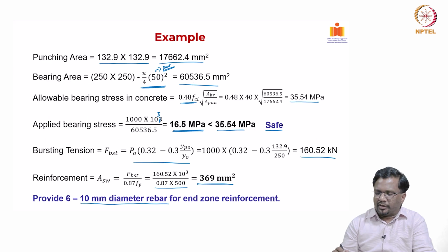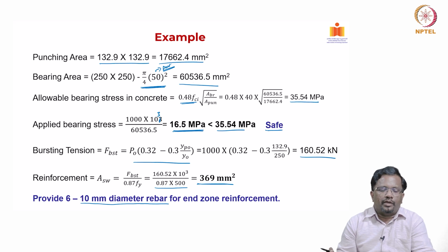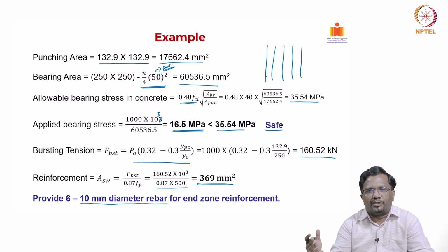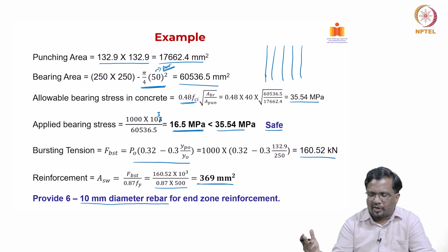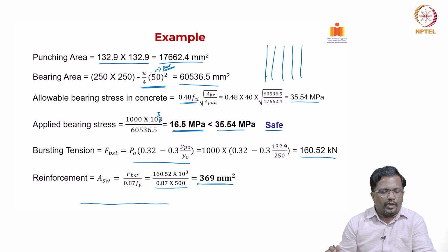Okay. So, basically we go ahead and put in the transverse direction, the same can be provided in the horizontal direction to actually confine the area. But actually for bursting tension you put only this vertical, like a stirrup. This should be in addition to whatever that shear reinforcement requirement is suggesting, right. So, I think the example is okay.